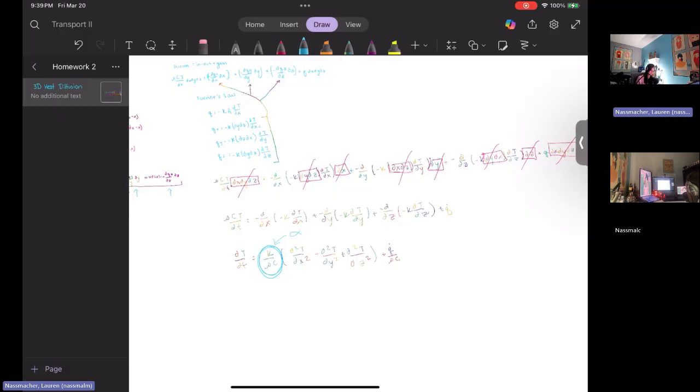And so our final simplified equation can be written as our 3D heat diffusivity is equivalent to our thermal diffusivity multiplied by our energy in minus our energy out through all dimensions plus our energy generated, which is our heat flow over our density multiplied by our heat capacity.